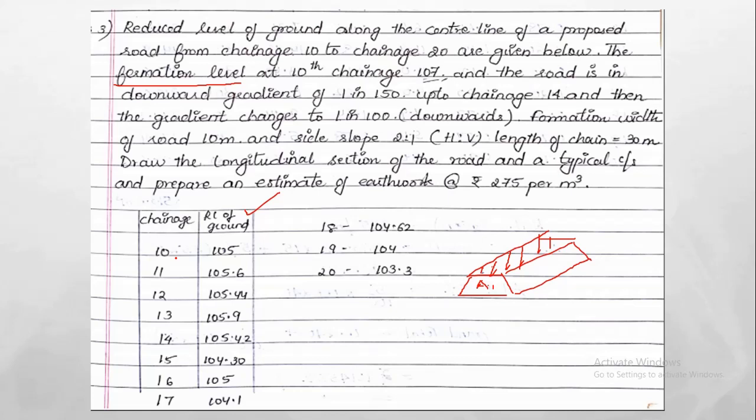So 10th chainage means the distance will be 10 into 30, if we are starting from 0, nearly 300 meter, because the length of the chain is 30 meter. One length is 30 meters. So after 300, we are considering that section from 10th chainage to